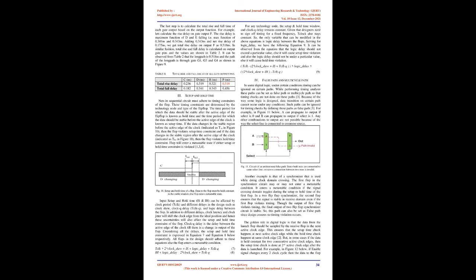It can be observed from the equation that the logic delay should not exceed a particular value, else it will cause setup time violation, and also the logic delay should not be under a particular value, else it will cause hold time violation. For false path and multi-cycle path.